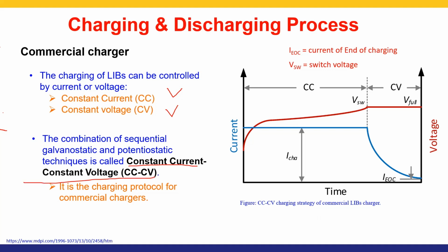If you apply a constant voltage to charge the lithium-ion battery in the very beginning, the current could be too high and the rise of temperature could cause some side reactions. Taking a step back, let's say the lithium-ion battery is not overstressed. However, the high C rate could cause a low capacity at the end of the day.